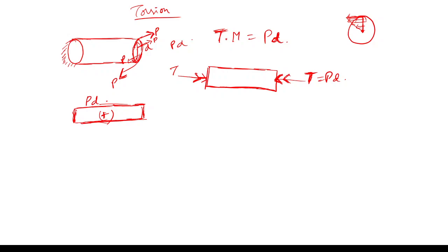So, sir, it has no relation with that at center. What will be the shear stress? No, at center the shear stress always remains 0 until and unless you have a direct shear. Due to twisting moment, the shear stress at the center is 0 because we are assuming a rigid cross section? No, no, no. This cross section is deformable only.